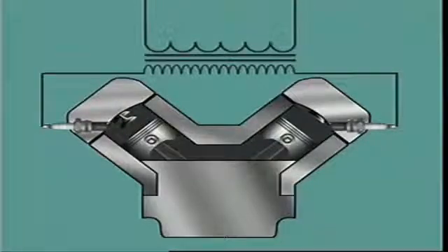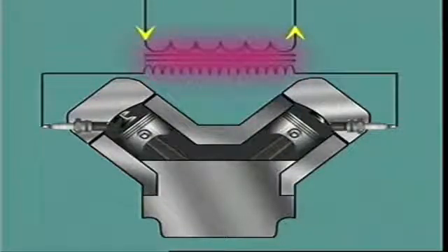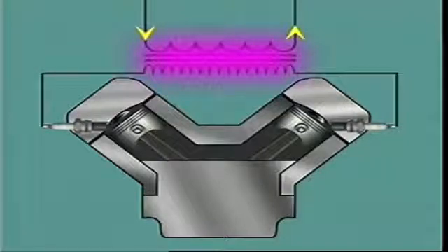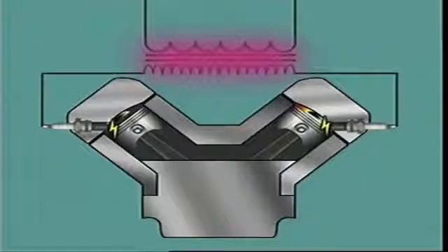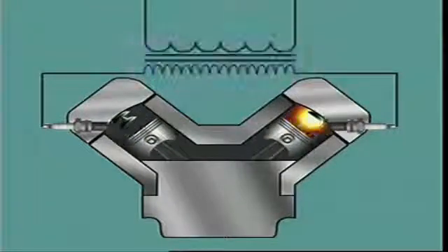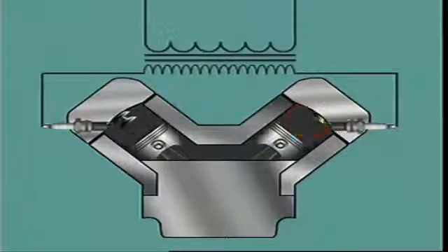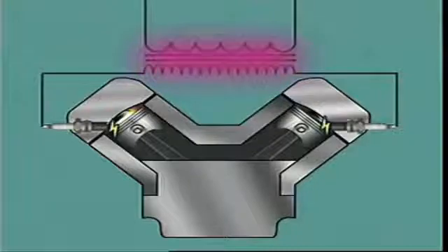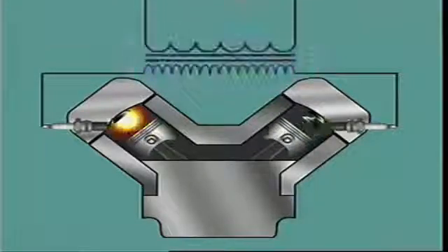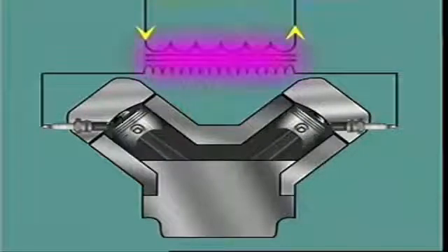When the crankshaft rotates through one revolution, the roles are reversed and the waste cylinder becomes the event cylinder. Firing of both plugs again takes place, and this cylinder now drives its piston down on the power stroke. This same process occurs on each pair of companion cylinders as they approach the top dead center position. Triggering of the primary circuit in each coil must therefore occur at the correct time in each crankshaft revolution.